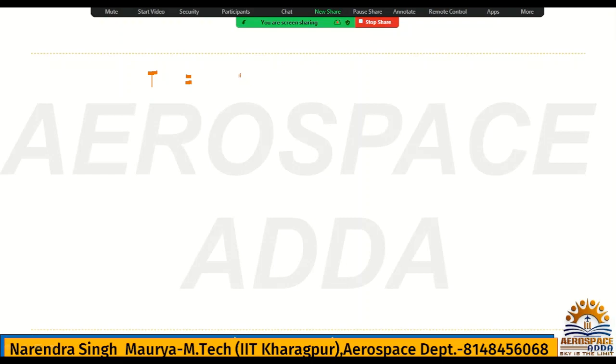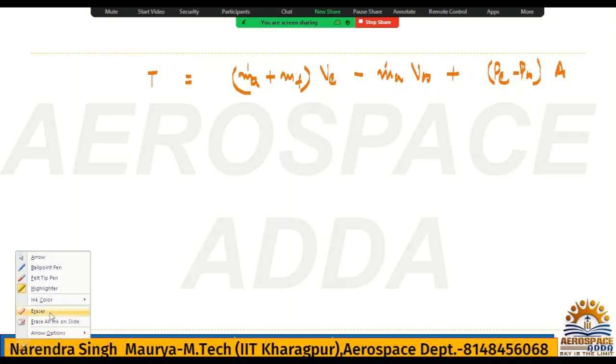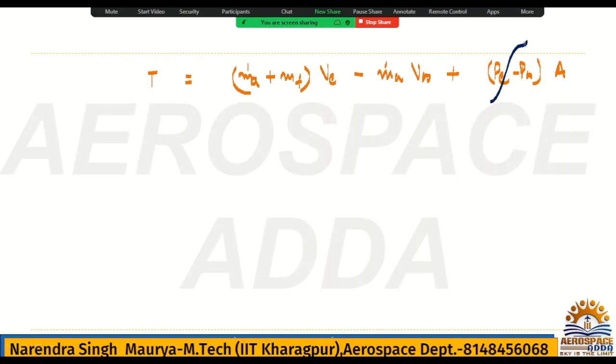The formula will be m dot a plus momentum thrust into VE minus m dot a into V infinity plus PE minus P infinity into area. Yes or no? So if you check for the static thrust, this part will be 0 because it is equal, and this velocity component will be 0.